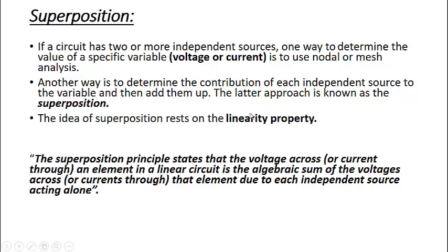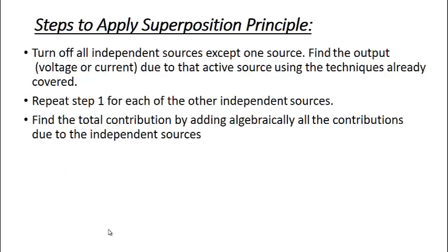voltage or current. The superposition principle states that the voltage across or current through an element in a linear circuit is the algebraic sum of the voltages across or currents through that element due to each independent source acting alone. This is the nutshell of the superposition theorem.